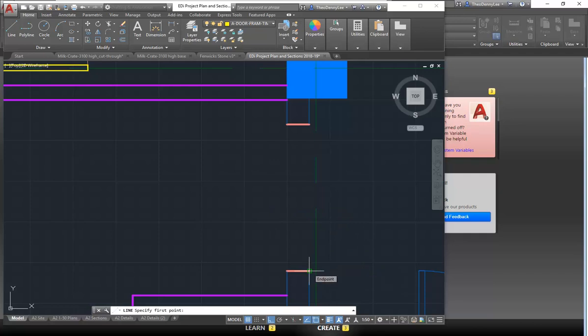So do you all remember the thickness of a door jamb? What's the standard? Exactly, spot on, yep. So 40 is the important one. 100 is the other direction that's standard as well, but I might make it a bit different, you'll see why. So I'm going to start there, come up 40, and then coming across to the left, because this wall's a bit thicker, it's 130, so I'm just going to make it 130. Again, we're trying to keep it as simple as possible graphically, and so that's the idea there. And so 130, and then back here.